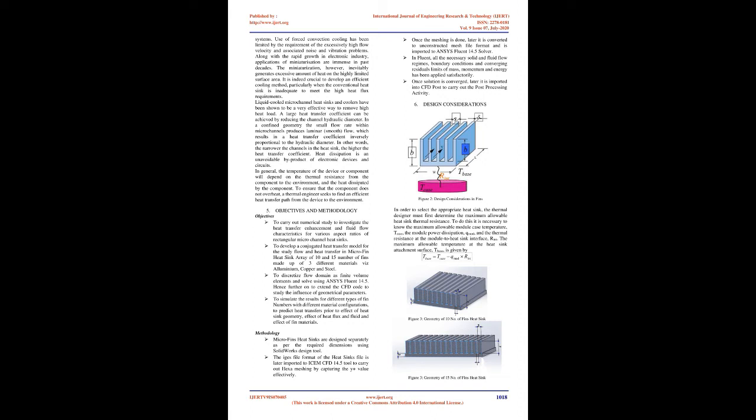In the proposed approach, A. Statistical methods were applied for the sensitivity analysis of the design factors, B. The design of experiments, DOE, and the response surface methodology, RSM, were used for the development of regression models of the thermal resistance and pressure drop in terms of the design factors and, C. The gradient-based numerical optimization technique was employed in the search for optimal design parameters.